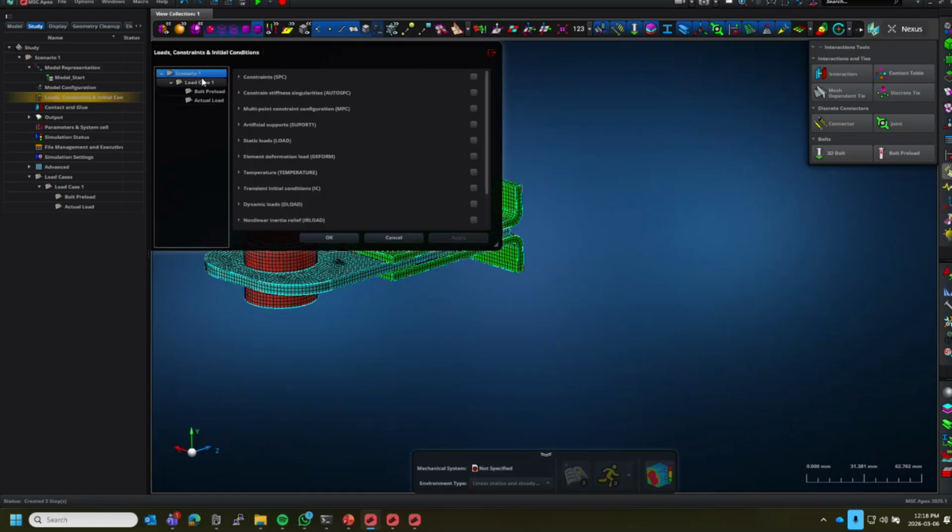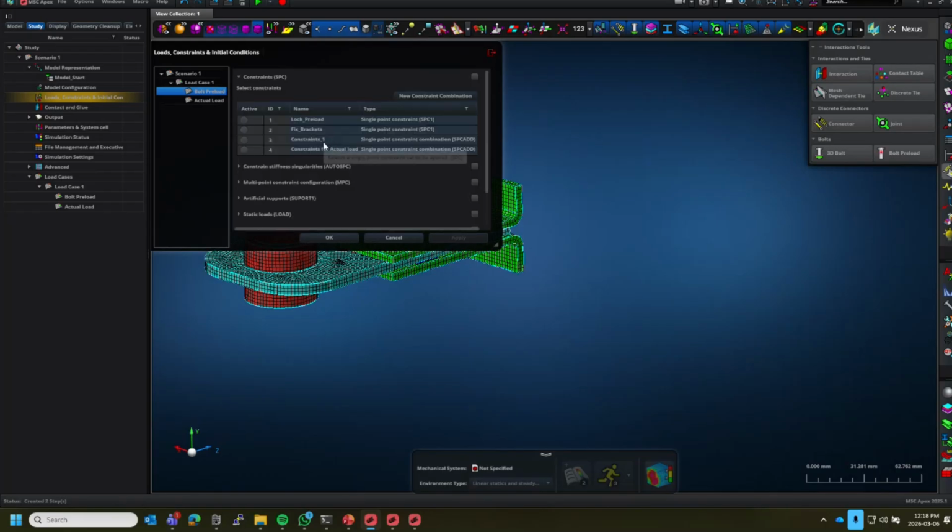And the way that Nastran works is, if I'm on this level, in other words, before the first load case, activates something like a constraint, it'll be active in anything unless it overrides it. So if you want to be certain, don't specify anything, rather specify it on this level, and I can say constraints. So that's that first one. I've got to change the name. So that's the initial constraint I want to apply.